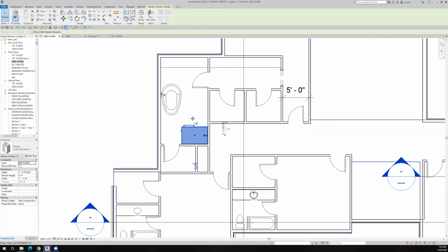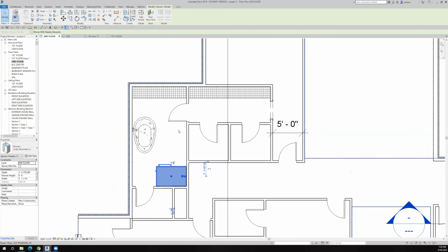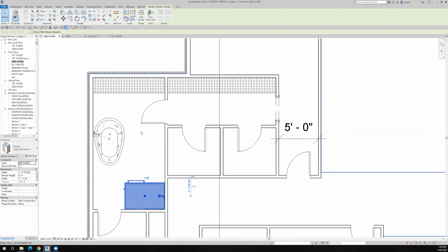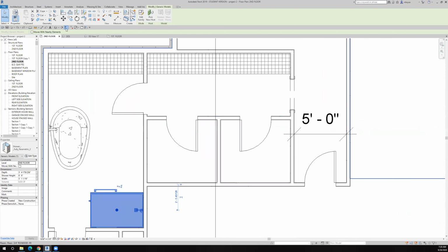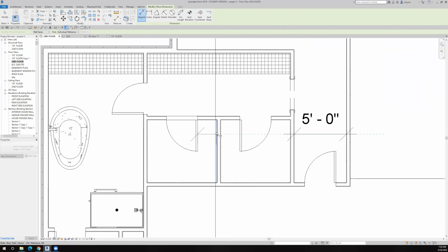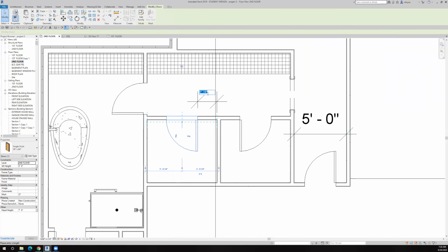So looking at what we have here, some of the things that are just standard pet peeves that I like to do is that this door swings into this space, and if I can move this door back this way, it'll have a wall to open up against. And so what that means is if I take this door and change it so that it's over here by 6 inches, so I'll change that. Remember, I like to have 6-inch returns for casing.